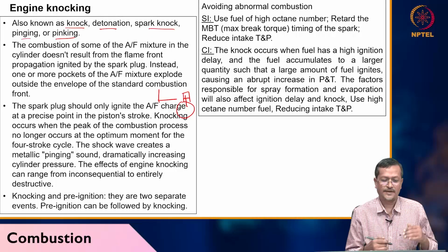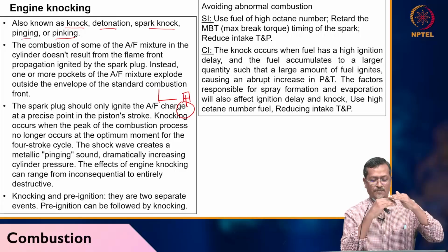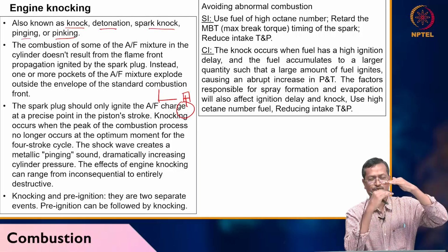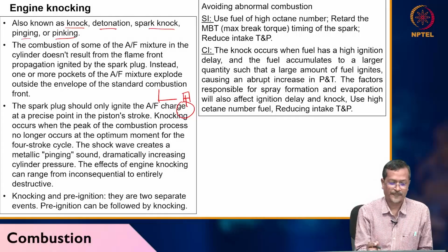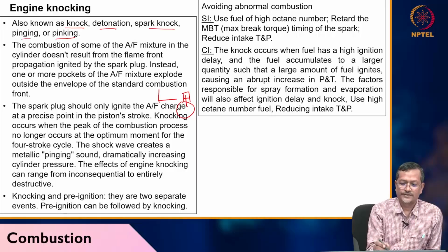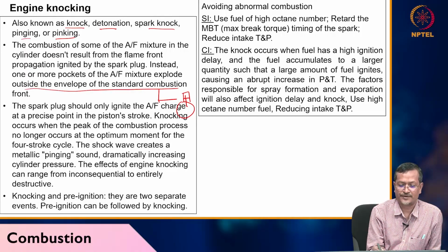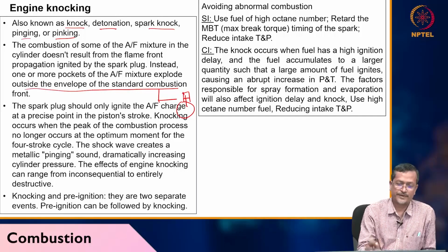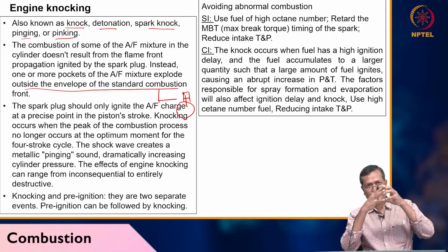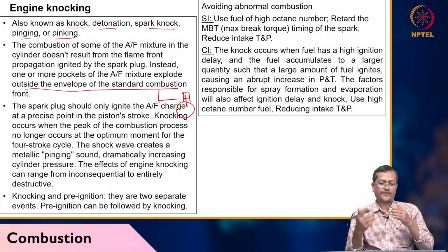The piston has not reached the top, but your fuel burnt, so it is pressurizing while the piston is moving up, and some energy will be lost. So instead, one or more pockets of air fuel mixture explode outside the envelope of the standard combustion front. Once the spark starts, the fire will propagate in a few microseconds or nanoseconds, but if the fire happens before that, that will be a problem.